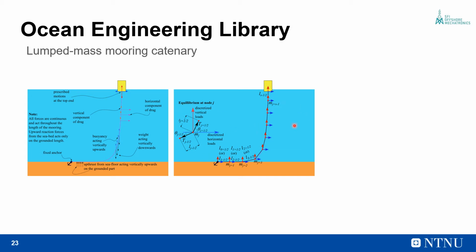From the equilibrium equation for the nodes, the equations of motion for the nodes are formulated and solved subject to the constraint equation that the links are inextensible. We adapted this method from the method presented by Walton and Polacek in their paper early in the 1960s. They had presented the method for a generic subsea cable structure without interaction from the seabed. To simulate the seabed interaction effects, we adapted the method suggested by Khan and Ansari in their work, where the reaction from the seabed is modeled as vertical forces applied on the interacting nodes.